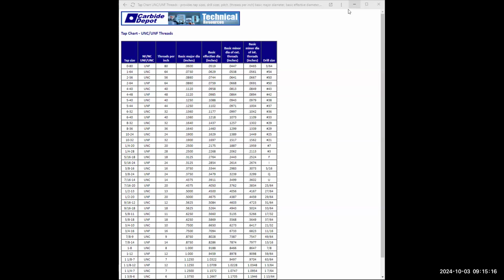All right, here we go. Gonna type in leader, enter. We're gonna type in near, NEAR, enter. Do it about right there. Click, turn off F8. Make it about the same angle as the other two.